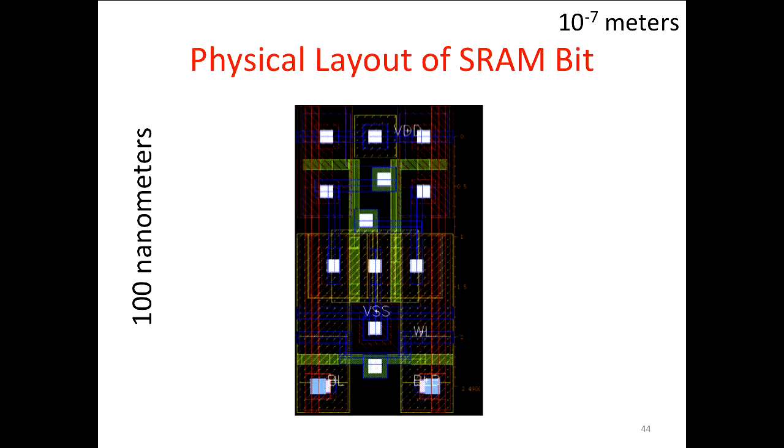And this is usually one of the most critical components in any new technology, because most of a chip is memory these days. Like all those caches, those huge memories. The L1 caches, the outer caches, the register files, they're all SRAM-like structures. And making those dense is really important to the cost. So people spend their lives optimizing how these things get packed together.